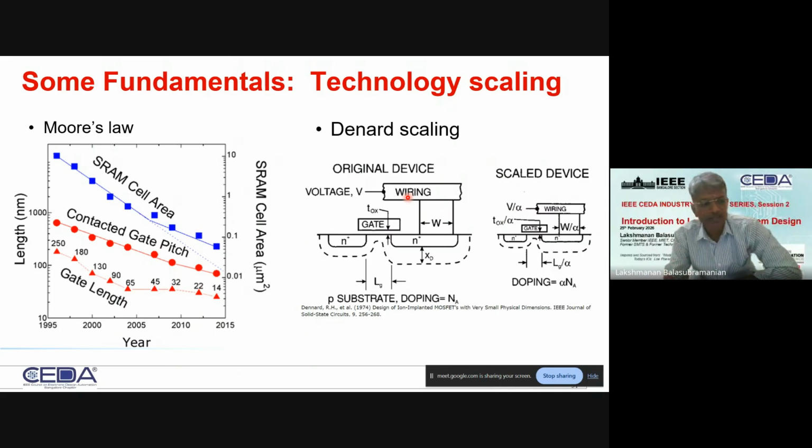But we got a very high level trend from Rajila when she discussed scaling: for a given functionality, you can compress more into a given die area, which means the individual device sizes are getting smaller, and hence you can put more and more devices into a smaller area. The channel length is reducing, and the thickness of the gate is also reducing, and given all this and the oxide material, your operating voltage reduces, because of the breakdown voltage, you cannot operate beyond a certain voltage.